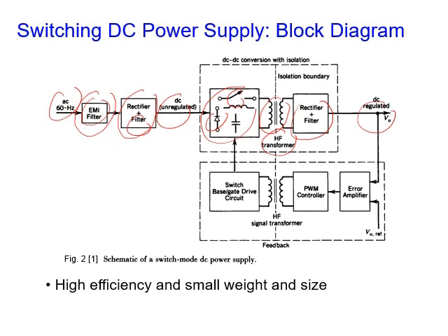Now usually in this type of DC power supply, we need to have negative feedback, as you can see here. We compare with a reference to get the error, and then this error goes to the pulse width modulation controller to control it, because we need to control the switch duty cycle. If you remember, T on, which is D times TS over TS, we need to control the time for the switch to work on and off. Again, high frequency transformer, and here is the circuit used to control the switch.